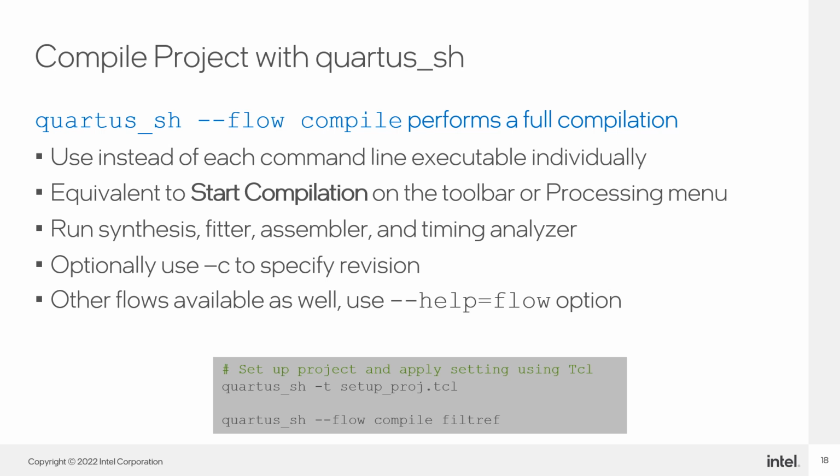Alternatively, instead of running each of the individual command line executables separately to compile a design, we can also use the quartus_sh executable with the --flow compile option to run the entire compilation process in one command. This is equivalent to pressing the Start Compilation button in the Intel Quartus software GUI toolbar, and it will run the synthesis engine, fitter, assembler, and timing analyzer. There are also other flows available such as implement, finalize, and recompile. Check the documentation or use the help option of the command for more information on those.